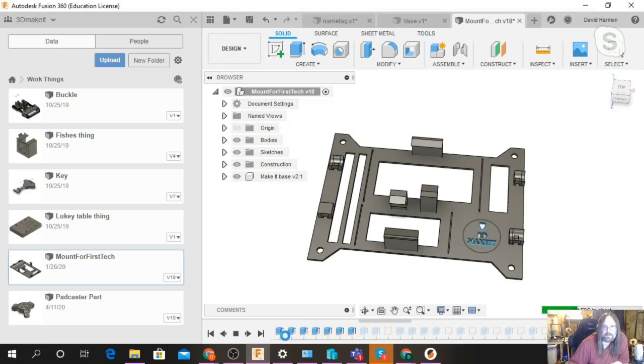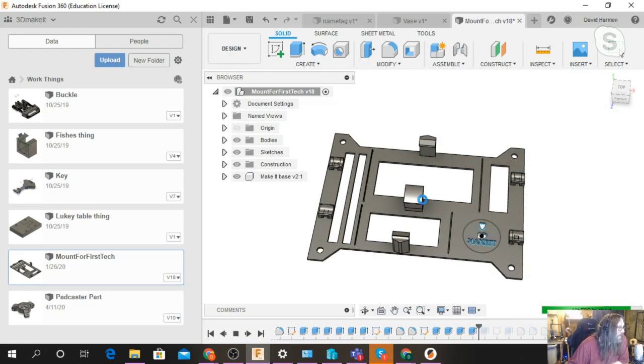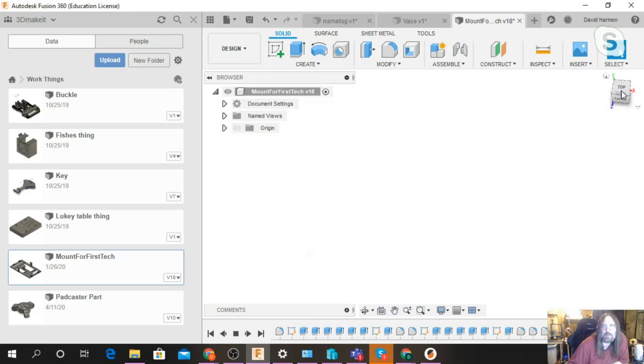And if you see the part that's building now, it's extrude, extrude, extrude, extrude, cut, new sketch, right? So literally your model is almost like a piece of clay. You're taking pieces away so that you can actually manufacture it. One of the last renditions we did was a problem with how it was 3D printing, and we changed the rigidity of some parts on the side. So when you're designing in Fusion, remember your 3D printer can print at a 45-degree angle very, very easily.